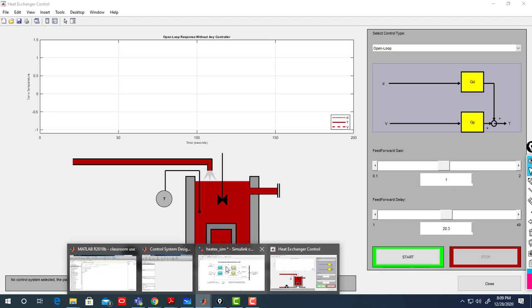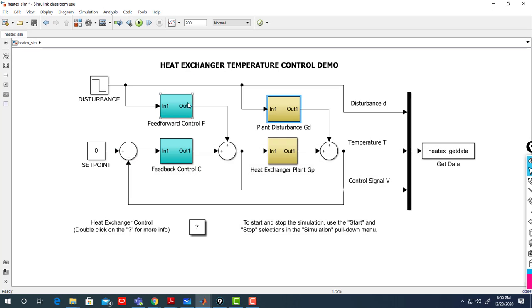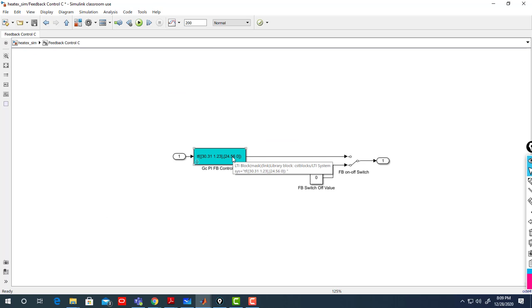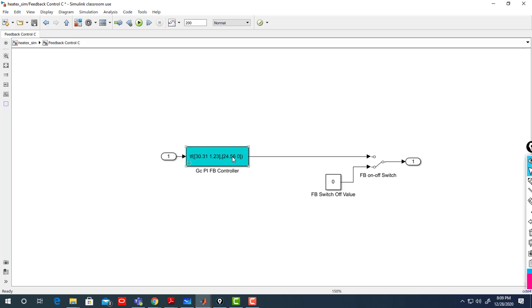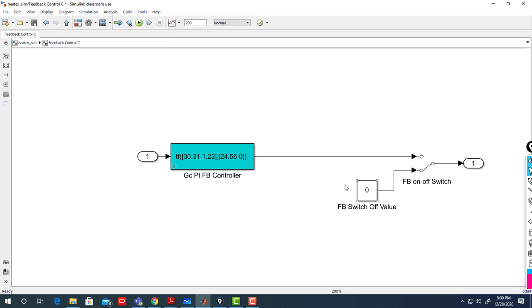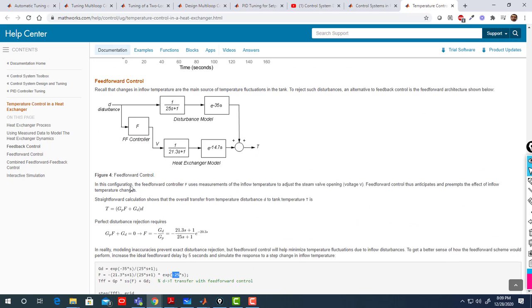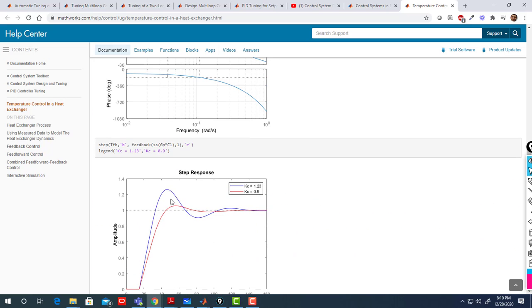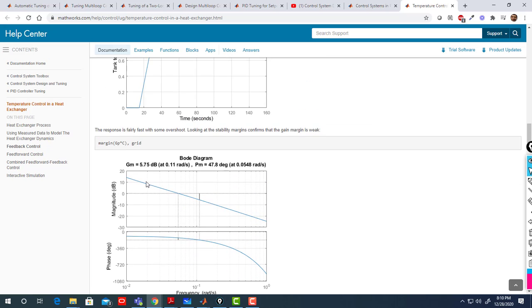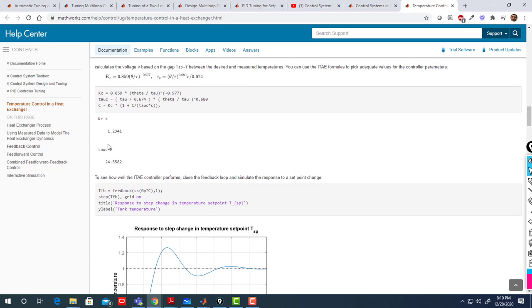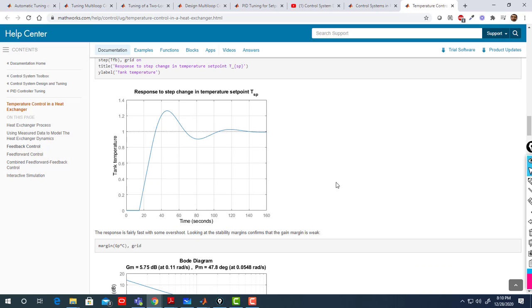Basically those will affect the feed forward control, the F that you calculated, even doesn't affect the feedback, because the feedback is something you calculated. I took the controller which we get from here, the feedback, the PI controller basically that we calculated in this tutorial.